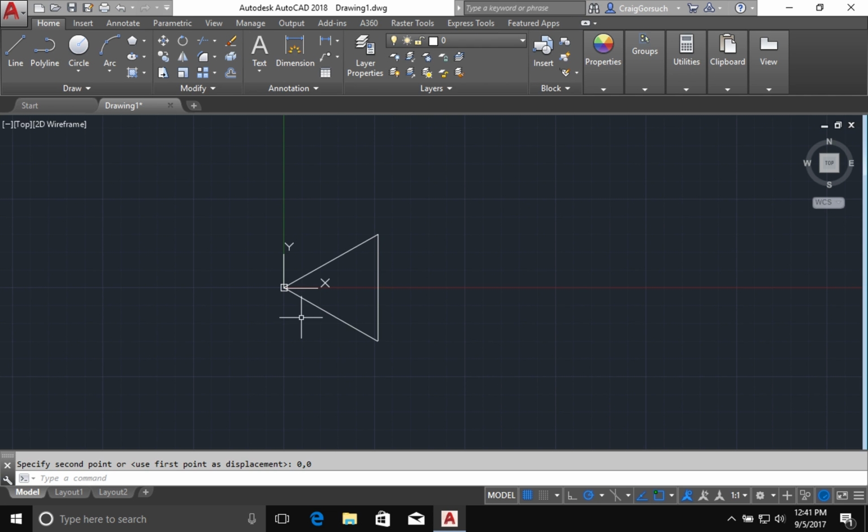I'm going to draw a line. This is just a temporary construction line. I want this line to be 6 inches long, starting at 0,0. Well, I know that the vertex of the triangle is at 0,0, so I don't need to key in a coordinate to draw this. L to start my line, push the space bar, same as pressing return. Left click to establish a beginning point of my line. And I'm going to hold my mouse on this angle, rubber banding to a nice 0 degrees.